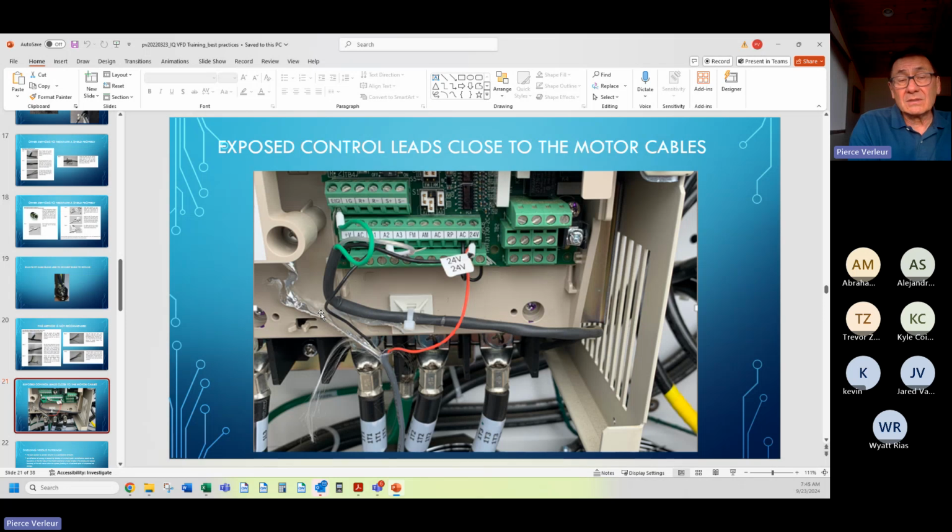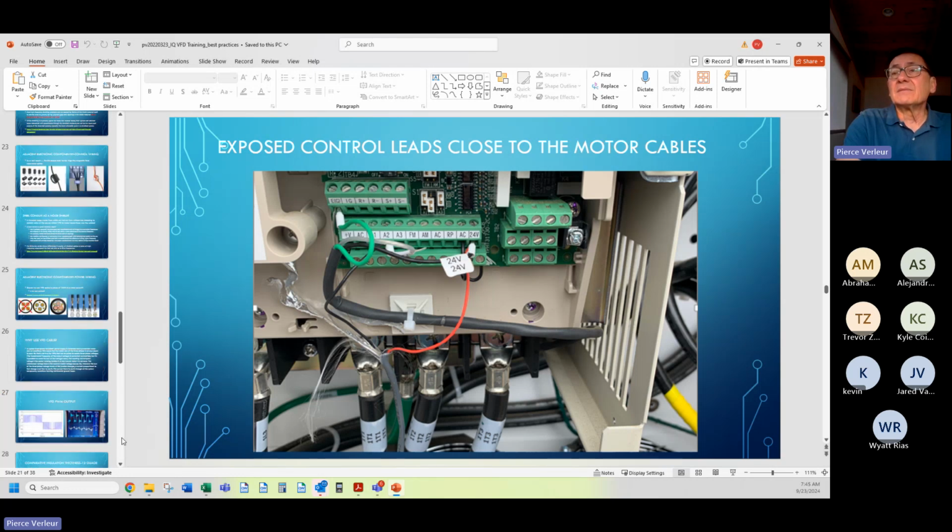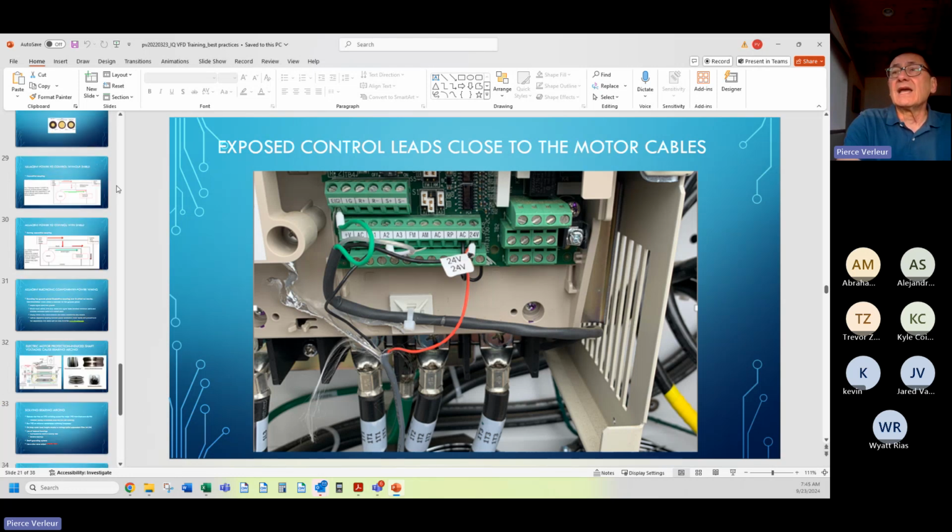You actually increase it. You trap more high frequency noise on the shield itself. Energy is going to go somewhere. When you trap that noise on the shield, you create the ability for the shield to have a capacitive discharge.